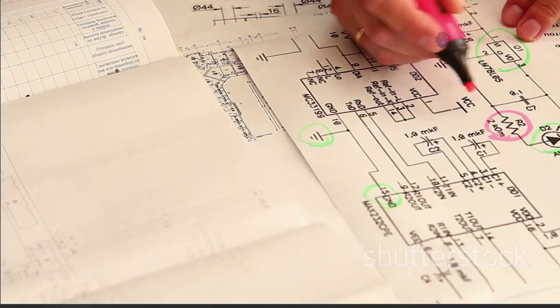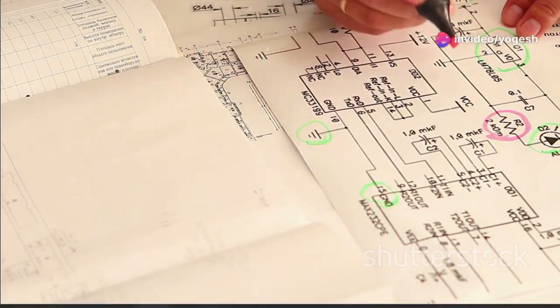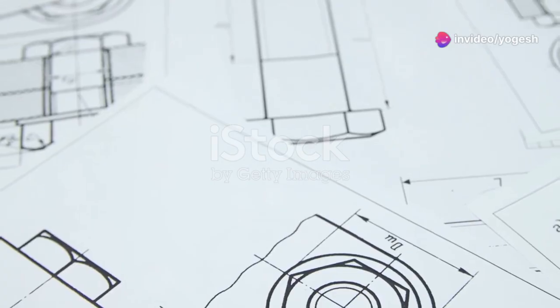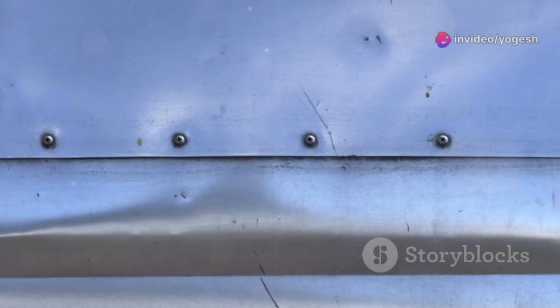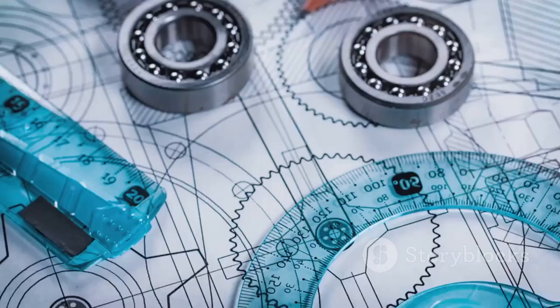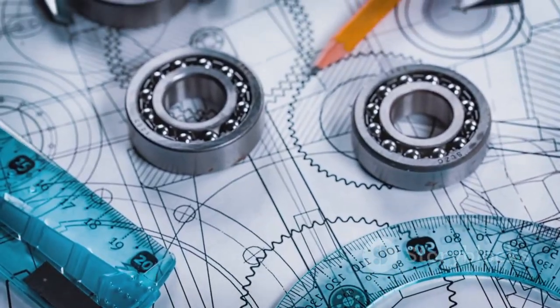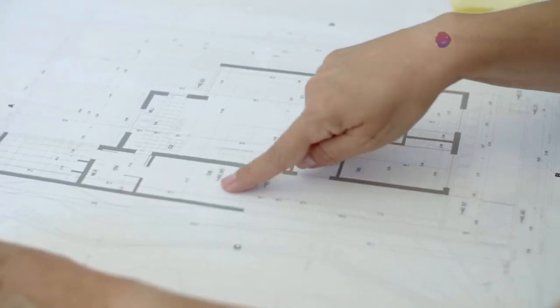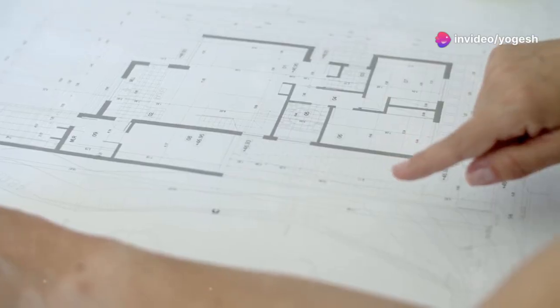Avoid common mistakes in sectional views. Incorrect hatching is a big blunder. Never hatch standard hardware or ribs parallel to the plane. Label views correctly to maintain connections. Dimension to visible lines, not hidden ones.